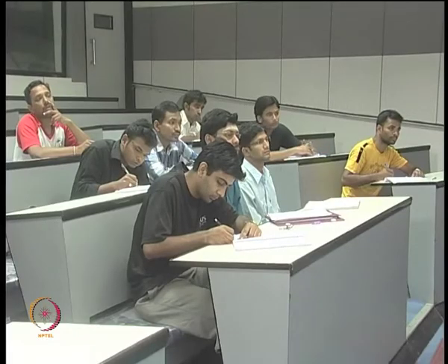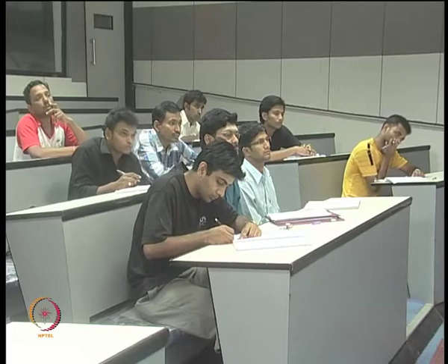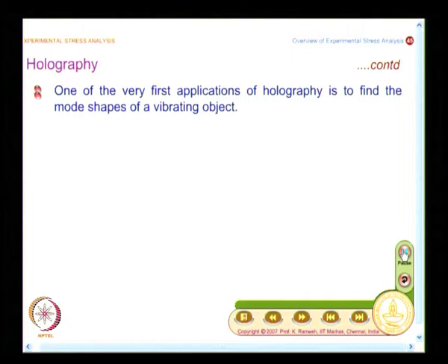When you look at the development, hologram interferometry's first application was on finding out the mode shapes of a vibrating object. One of the motivations for hologram interferometry as a stress analysis or displacement measurement tool was capturing the mode shapes of turbine blades, and Carl Stetson and others have contributed significantly in this area.